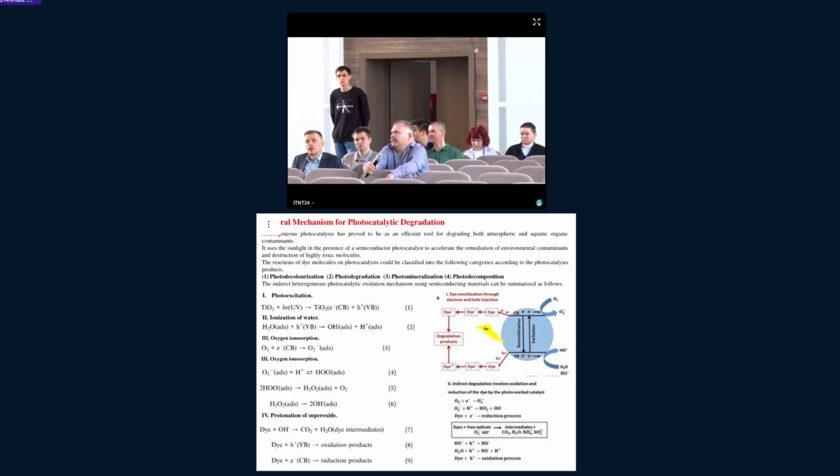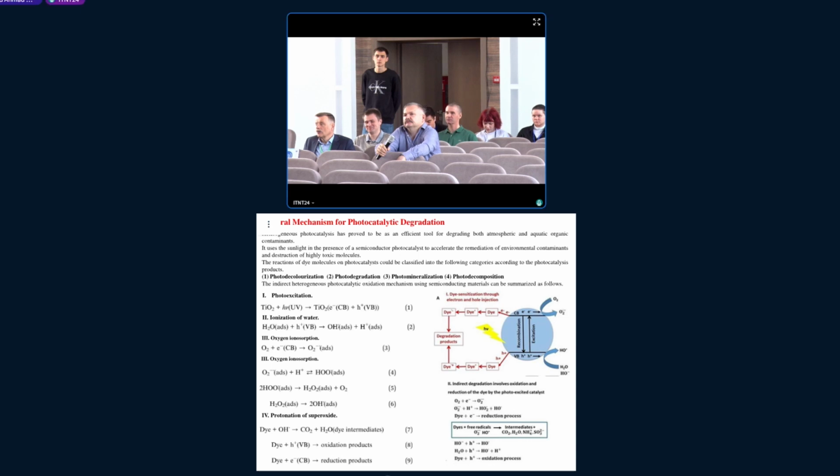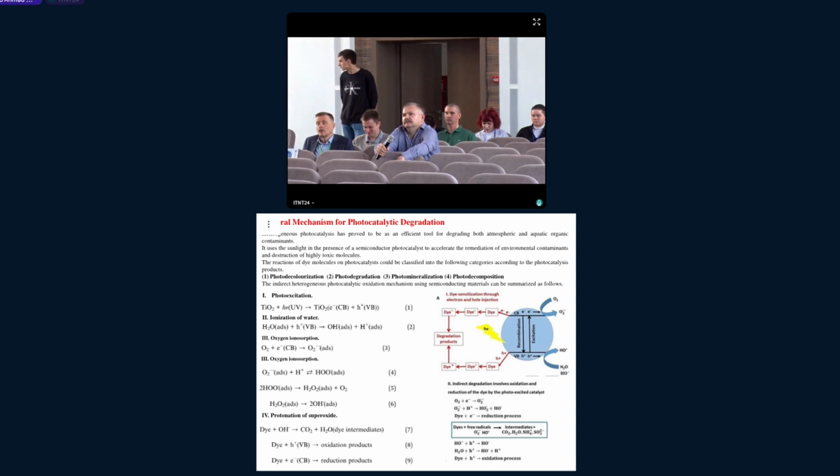it depends upon the size difference, the lattice parameters. When there is a difference in the lattice parameters of the systems, whether the host material and the dopant material, that plays an important role, the strain, because there could be the deformation of the size also. The structural deformation can take place, the tensile strain can take place. So that plays an important role there. So it depends upon the type of material you are doping and its compatibility with the ionic radius, the size of the host material and the dopant material. Accordingly, you can say whether it is a better photocatalytic material or not.